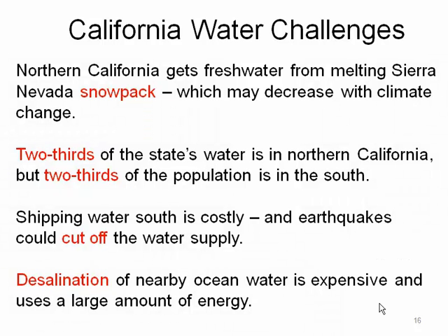California, especially Northern California, gets most of its incoming precipitation in the form of snow, largely in the Sierra Nevada. Approximately 80% of the water that California manages comes from that snowpack. And as you can imagine, if global temperatures are increasing, that snowpack will be diminished and more precipitation will fall as rain. The problem is that the current system of reservoirs and canals that move water around is devised for a snowpack dominated regime, where water is stored in the form of snow over the course of the winter and gradually released into the start of the growing season.